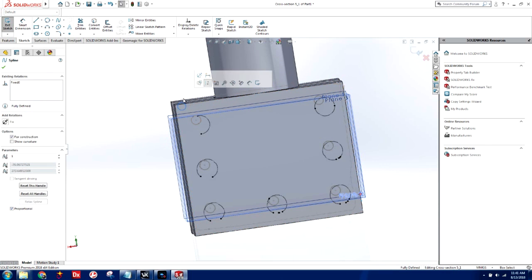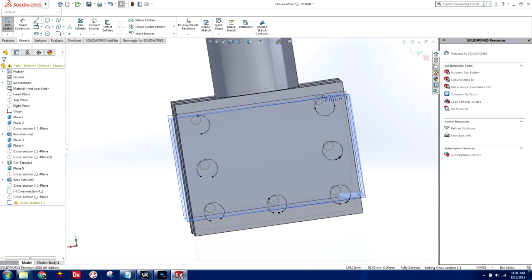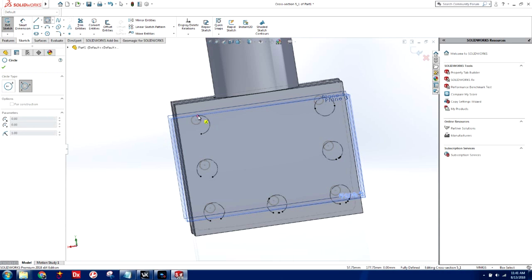So I can use my circle tool, just like I did before. Now, obviously, because we are modeling inside of SolidWorks, I can set a constraint to make all of these circles equal radius, and I can have construction geometry, a construction line, to make sure that they're all aligned to each other.